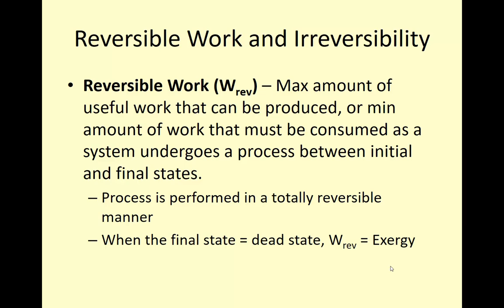But if the final state is equal to the dead state, meaning there's no other additional energy that can be extracted from this system because it's at thermodynamic equilibrium with its environment, then our reversible work is equal to our exergy. So that's how we determine the potential energy possibilities of a system. Because if that system is not in thermodynamic equilibrium, let's say there's a pressure differential or a temperature differential between the system and our environment, there's still some usable work that can be extracted. It may not be a lot, but anytime your system's not at equilibrium with the environment, it has the potential to do work or to consume work.